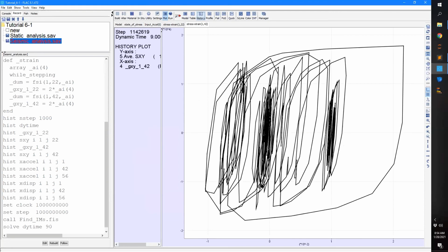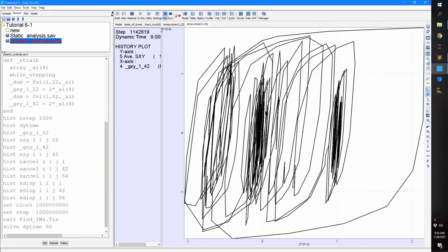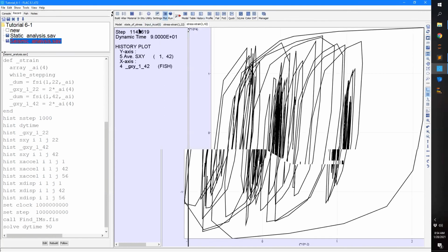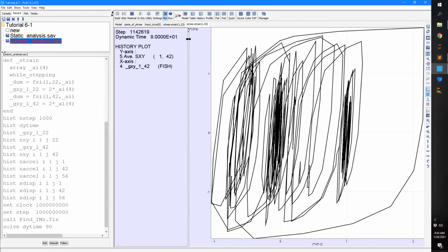And what we're going to find, and we will see this in just a moment, is that we have a layer where a lot of the high strains are being isolated between the softer clay and the stiffer dense sand below. So to explore that a little bit more, let's create a contour plot. I think that would be particularly helpful here.